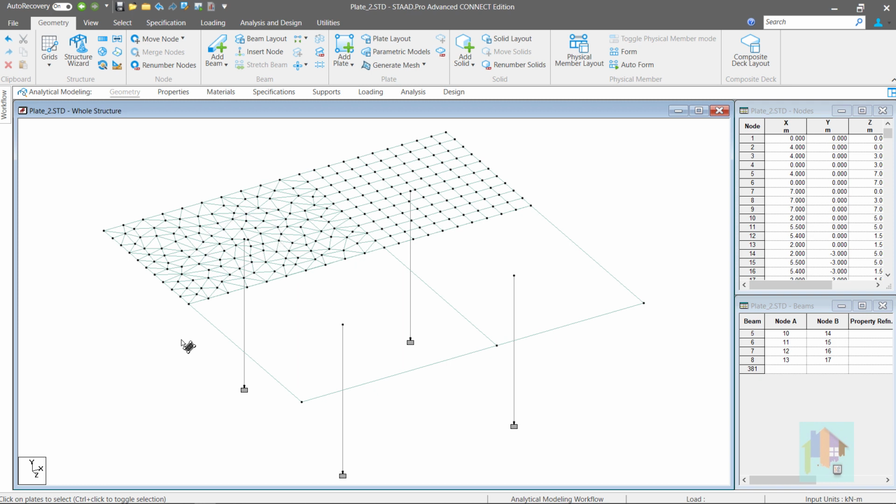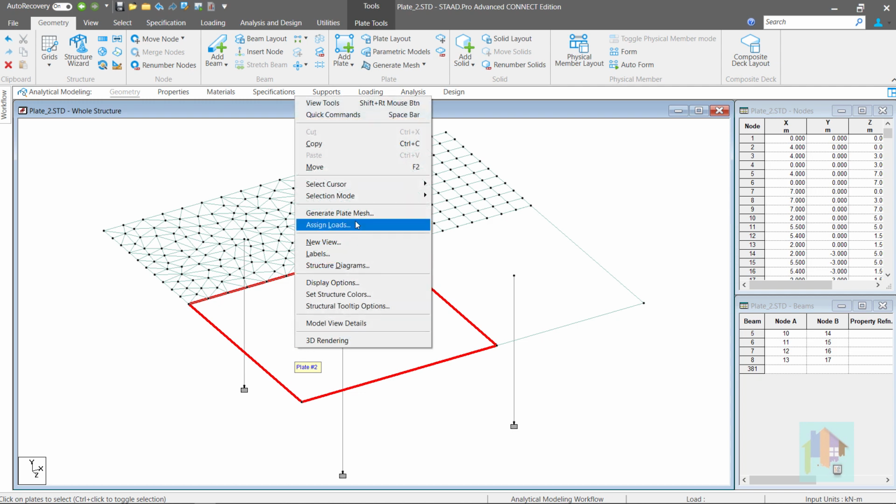If you want to divide the mesh in a line to apply a line load on slab, that is also not possible using this meshing approach. Lack of intelligence to identify existing beam or node during mesh generation. No option to generate meshing along a line or a region. These are some major limitations of the basic mesh generator.